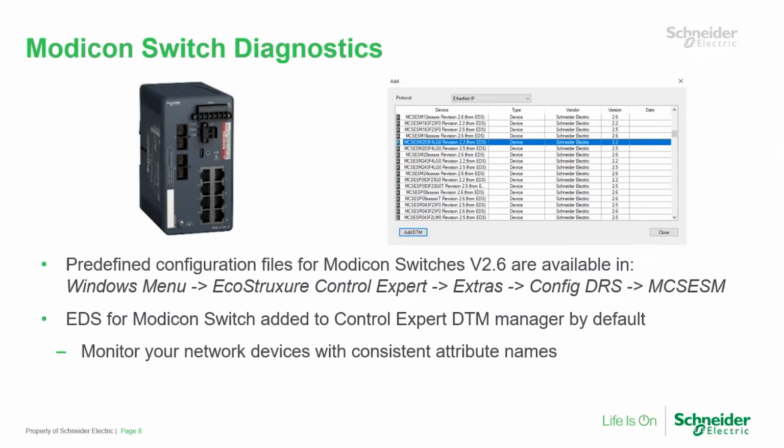For users of the Modicon switches, we have now installed with Control Expert the EDS files for getting diagnostics from the Modicon switches. And in addition, the dual ring switch configuration files are now saved in the extras folder for Control Expert, so you don't have to go out to the website and find those.